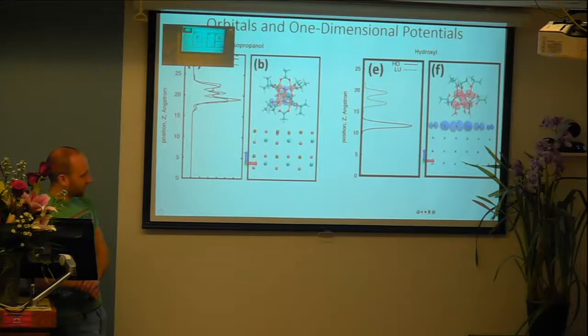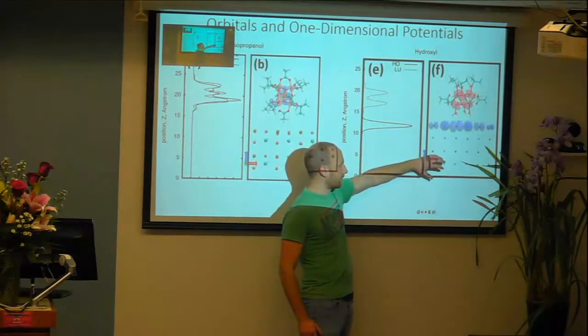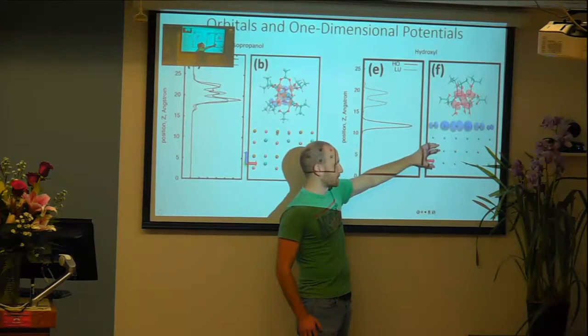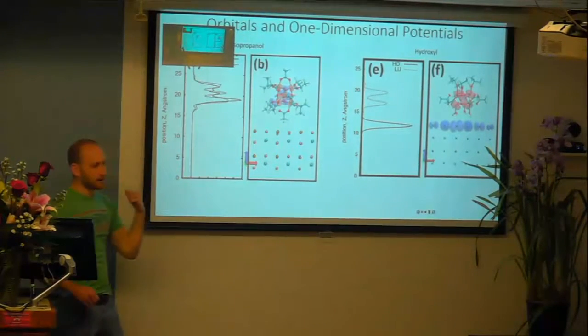You might have to run through that a little bit slower for me. I guess that was kind of quick. So the perovskite is the optical absorber in this case. The titanium dioxide is not in and of itself optically active. Then what's the purpose of your titanium dioxide? It's essentially, I guess this is sort of what you would want, so that you have an electron in here that gets excited and you want it to get naturally pulled away from the perovskite into the titanium dioxide.